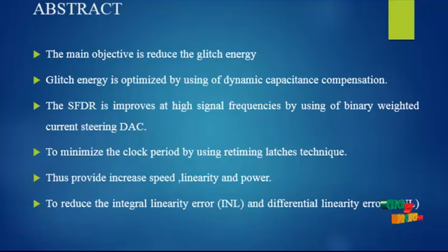The fundamental circuit of most D to A converters involves a voltage or current reference, a resistive ladder network that derives weighted currents or voltages, usually as discrete fractions of the reference, and a set of switches operated by the digital input that determines which current or voltage will be summed to constitute the output. The output of the D to A converter is proportional to the product of the digital input value and the reference. This design is carried out in CMOS technology in the Tanner EDA tool.